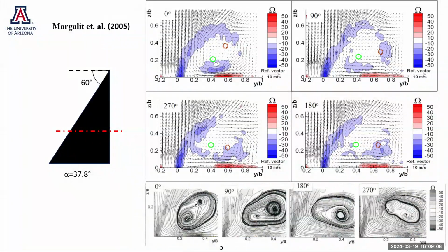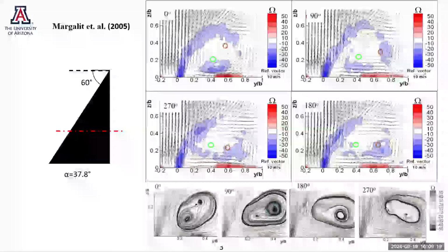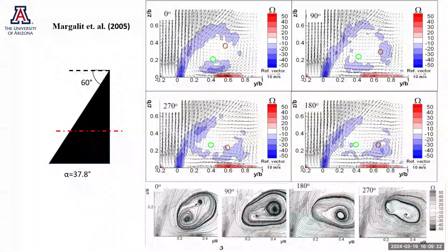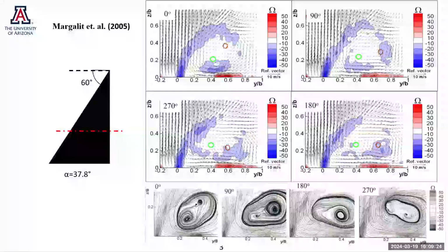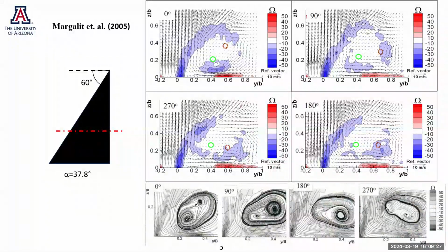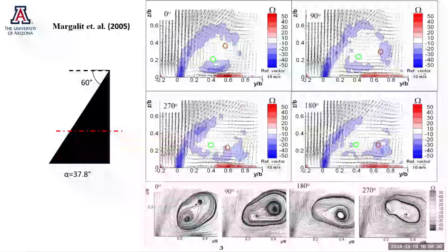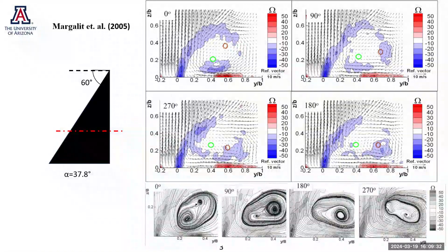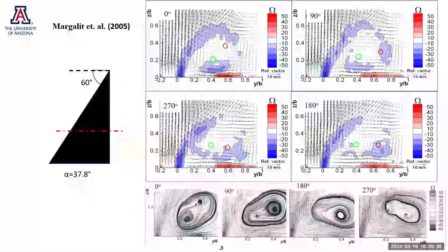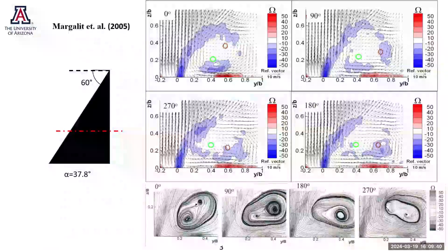Here, as I mentioned earlier, there are shear layers, and you can see the vorticity profile. This is one structure of a shear KH vortex, and you can see this is a negative vortex, that is, clockwise motion. You see another discrete vortex here for this particular phase angle of 0 degrees, so you see two discrete KH vortices. As we progress in the phase, these two KH vortices twist around each other. For 0 degrees, we see the streamlines here.